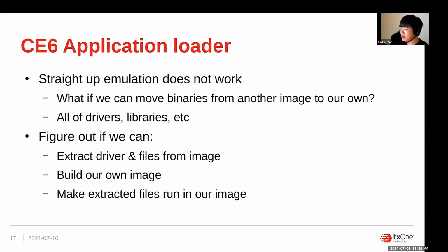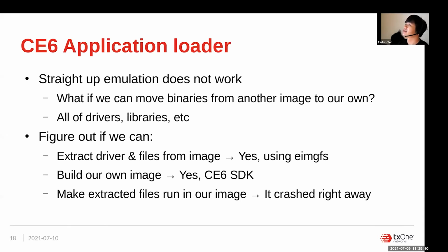Precisely said, the vendor actually invokes system and kernel flags on the files. So in order to achieve our method, we need to figure out if we can extract drivers and files from a CE image, bundle them into our own image, and make the files actually run in our own image. Fortunately, for extraction, we can use eImageFS. For building our own image, we have the CE6 SDK, which is based on Microsoft Visual Studio, and it is available to us.